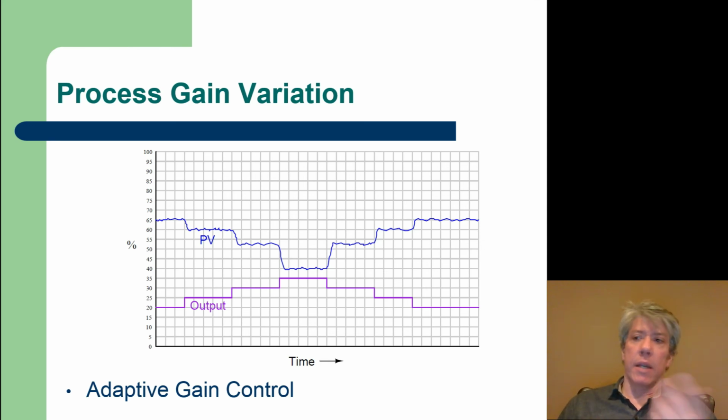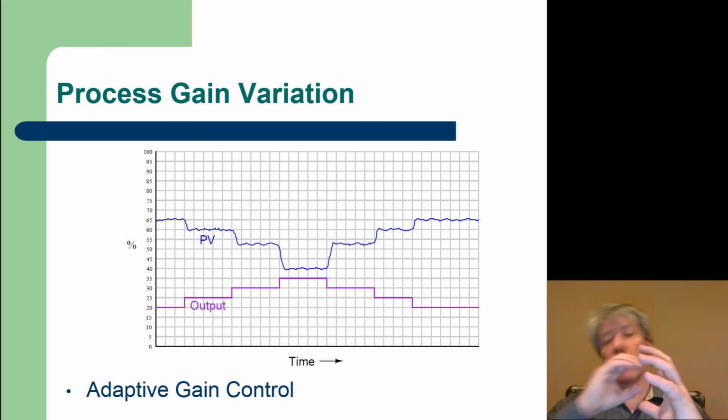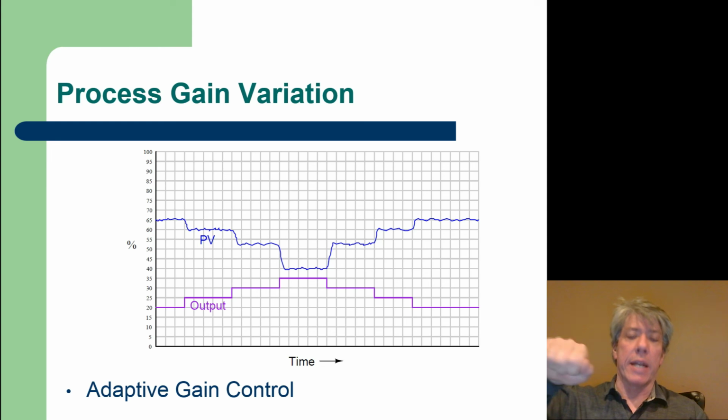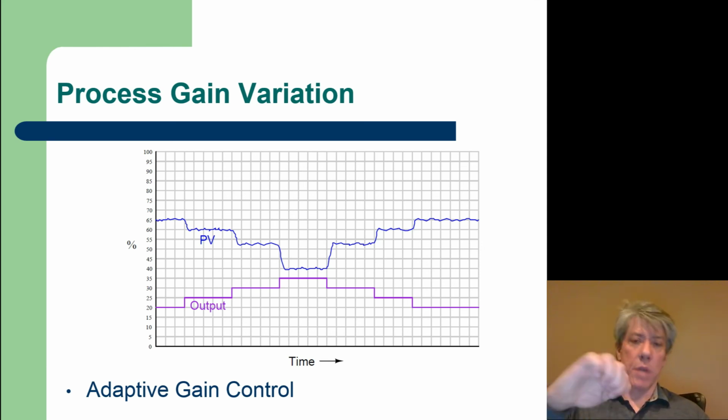But obviously control valves are nonlinear often, and depending on what type you have, especially a ball valve. A ball valve is just like it sounds, it's a ball. It's got a hole in it, and usually has a right angle handle on it if you're talking about a hand valve. And what you'll find with a ball valve is they're made to be either open or closed. They're not really made to control flow, although there are some special shapes in the holes through ball valves, triangle shapes and others, that can give you whatever characteristics you want of flow versus handle position.